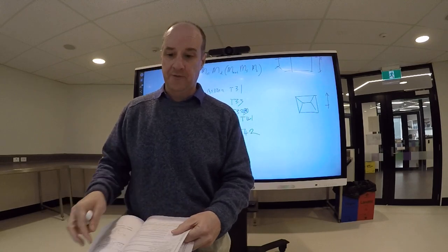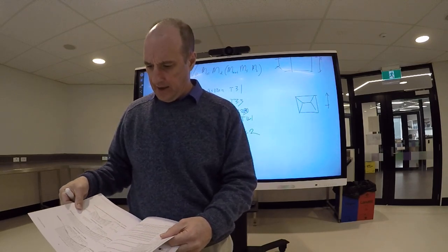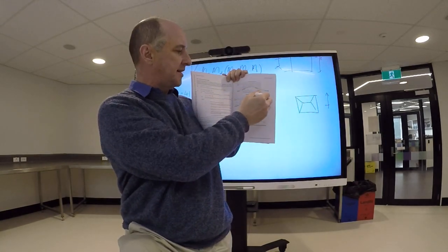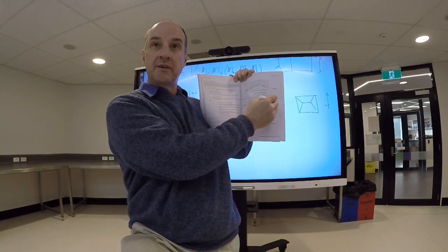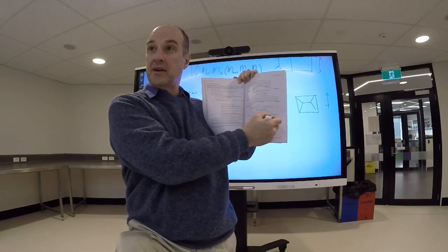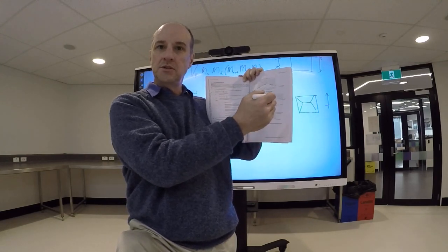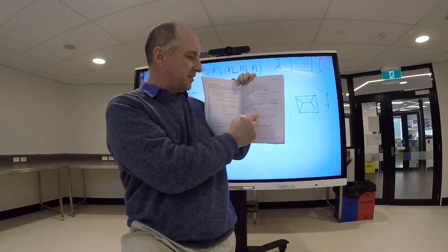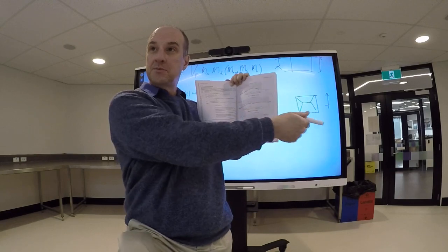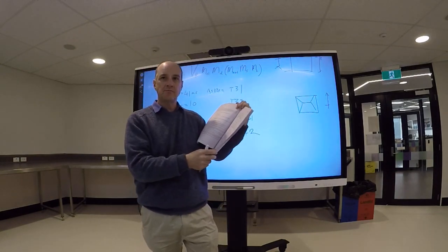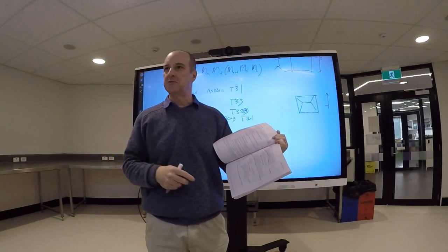It starts at section 4.4, and it varies whether it's an isolated hill like that, or an uphill slope and then flat, whether your building is on the front of the hill or on the back of the hill. If the wind is blowing west and you've got a house here, it's on the front of the hill, but if the wind is blowing east, then it's on the back of the hill. This is why you end up with different wind speeds from different directions.